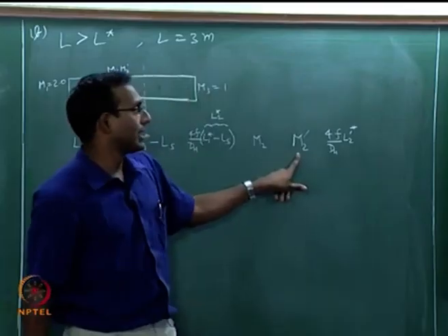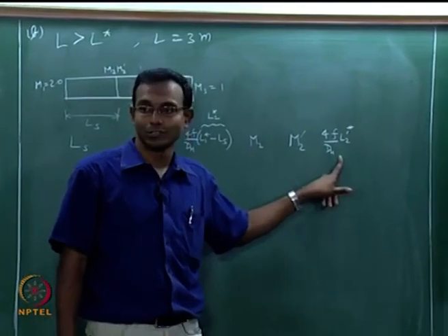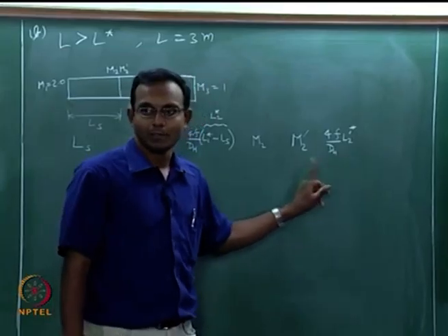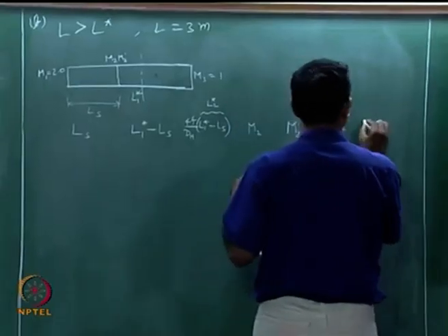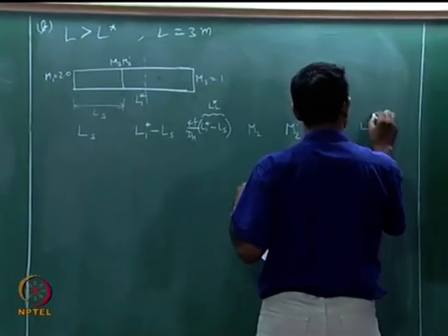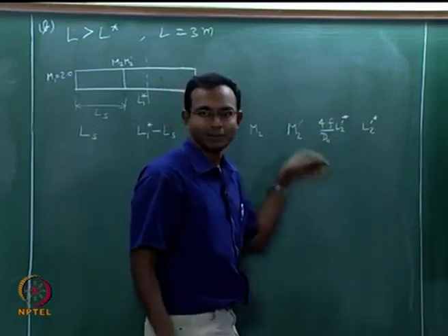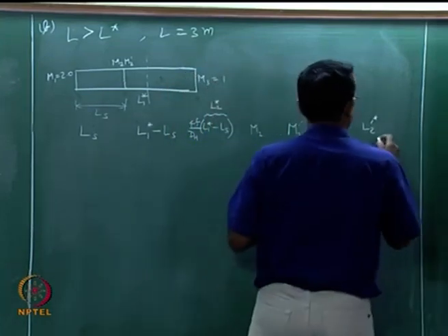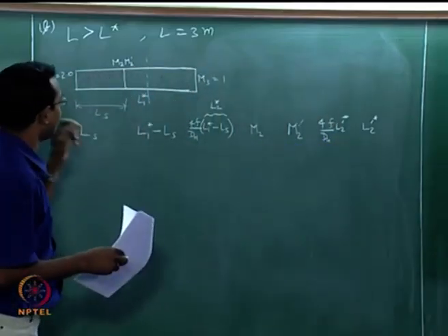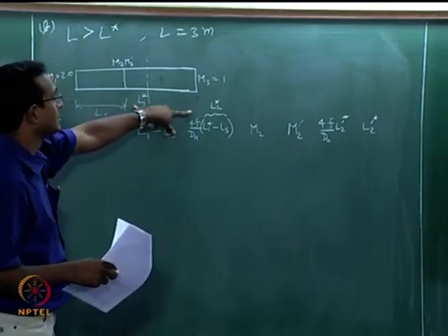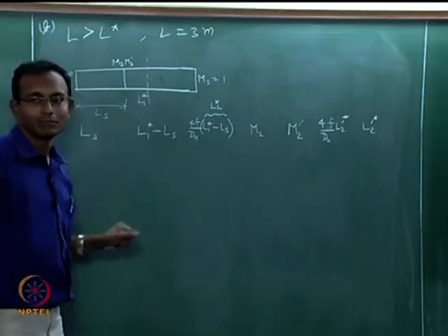From this Mach number I will go to Fanno flow tables, find this. Of course, now you have to pick only the subsonic solution. Okay, I will pick the subsonic solution from here, and from here I will get L2 prime star. I will just have to multiply appropriately Dh by 4f, you will get that. After all this, finally, I have to check whether this distance is more than or less than that L2 prime star.